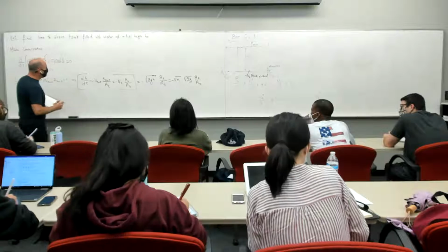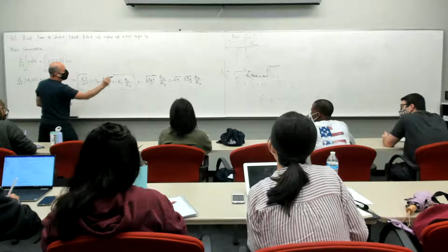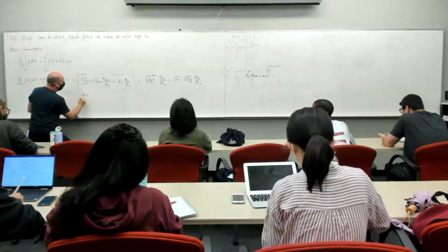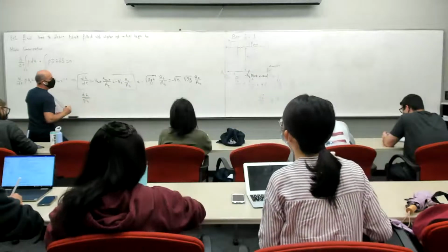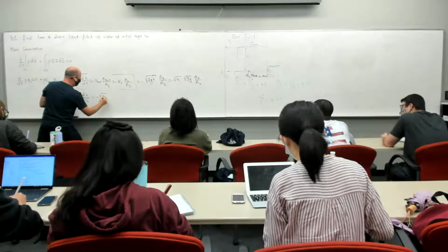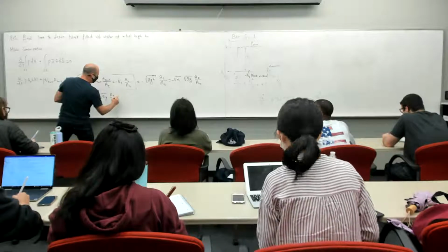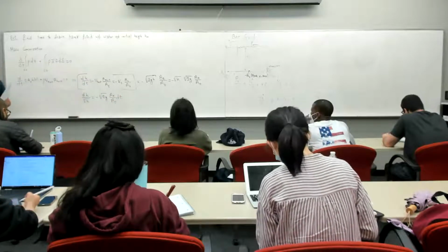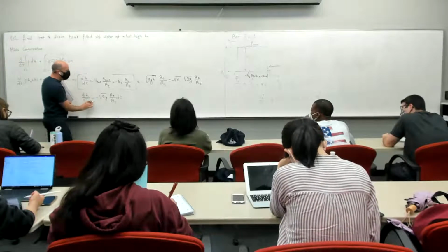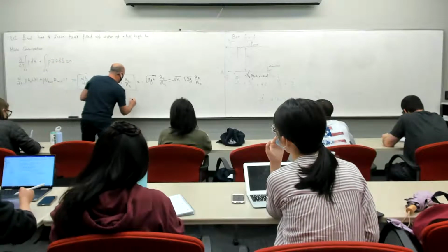So here's what I did. I divided by square root of h and I multiplied by dt. So you get dh over square root of h is equal to minus square root of 2g A exit over A tank dt. Really just a little mathematical trick. So now I have homogeneous terms here, so I can integrate them easily. So if you integrate,